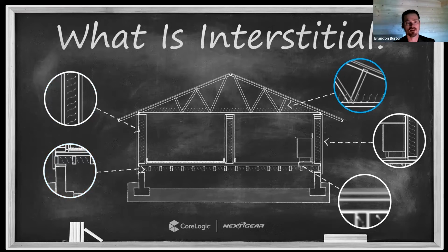Moving over to the right-hand side of the image, it's potentially an area that has to be dealt with as an attic space, depending on where the source of water is and how it migrated through the building. Cabinetry is an interesting one because it creates lots of interstitial spaces, potentially. Cabinetry and built-ins both, where we have the area down beyond and behind the toe kick. We also have the area behind the paneling on the back side of the cabinets, which can be an entirely separate and independent affected area or interstitial cavity or space.